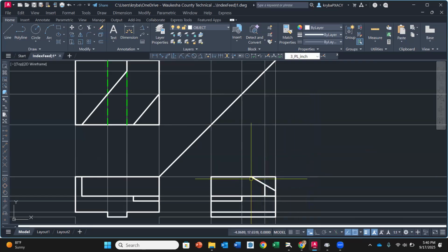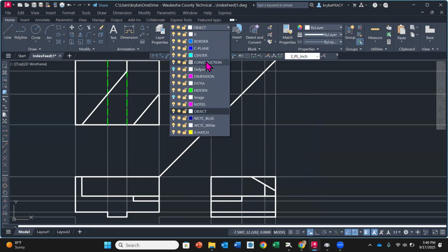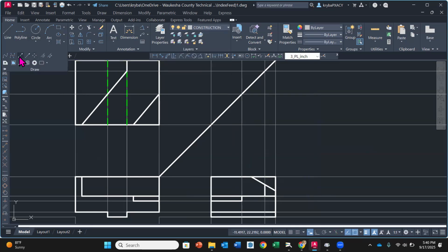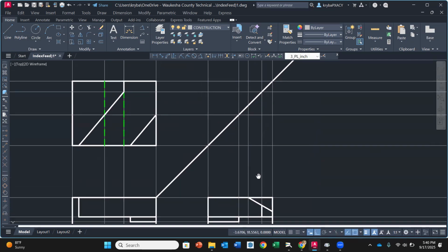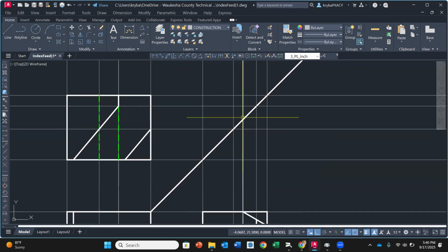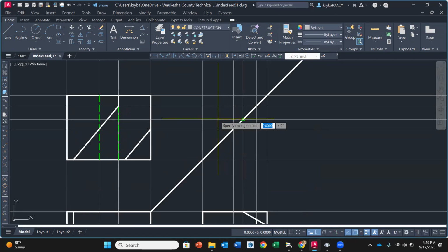that was that 0.94. So we are going to draw a construction line going straight back up over our miter line where the intersection of that 30-degree angle was. So I got to go ortho over the top. So it's that line there all the way up, and then another construction line going horizontal.